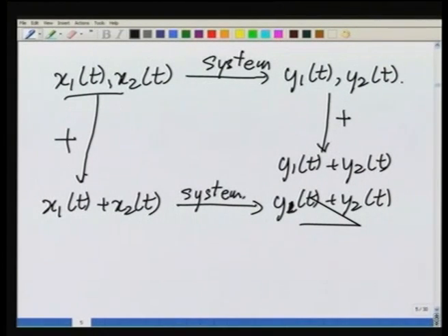If the end result is the same irrespective of the two paths, that is when you would say that the system commutes with that particular linear operation, namely addition in this case. So, if you test whether the system commutes with addition as well as test if the system commutes with scaling of the input, then together we have succeeded in showing that the system is both homogeneous and additive and therefore linear. Let us work out a few examples using the commutation diagram, and that will help us understand how to use this diagram.